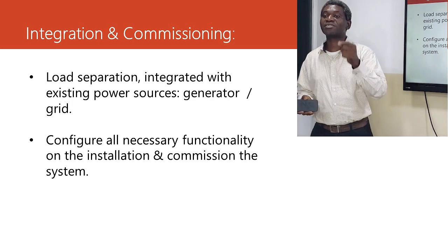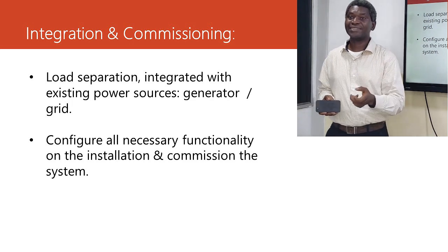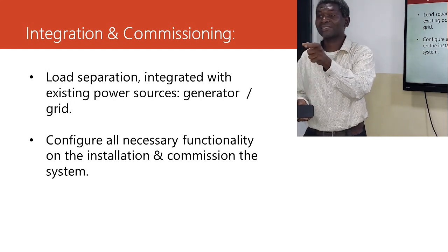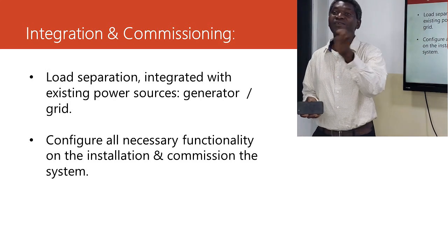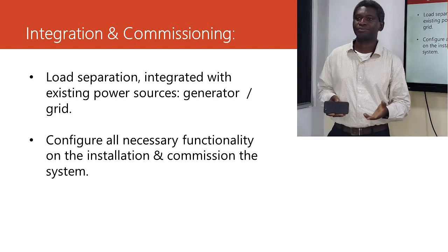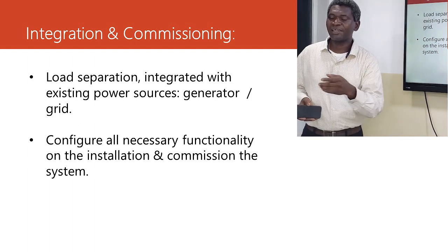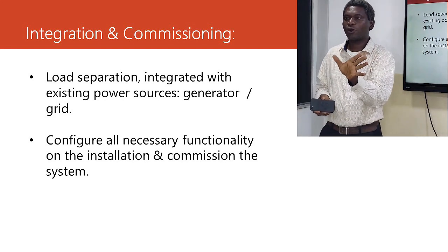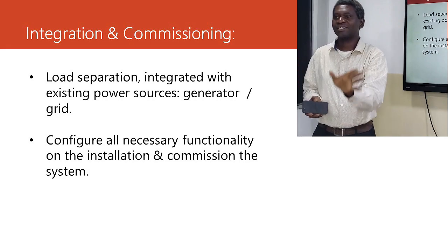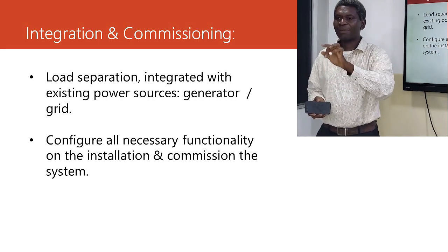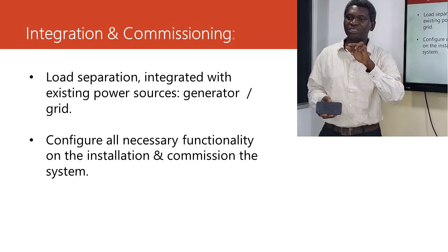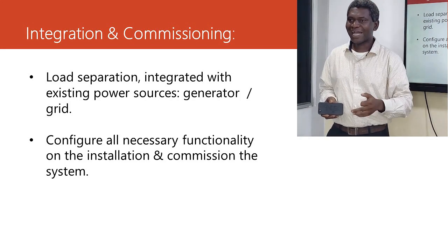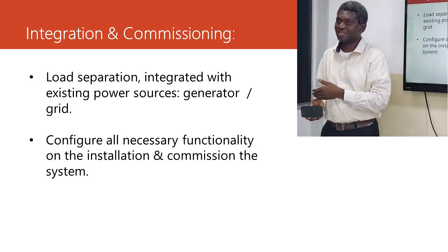We have seen situations where we have installed a system that is supposed to be configured as lead acid, and we leave it as user defined. You might not understand what I'm saying, but in the inverter itself, there are functionalities and options that you can choose by pressing the buttons on the inverter. So make sure you configure the inverter according to what the manual says.